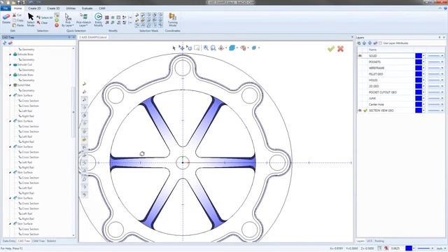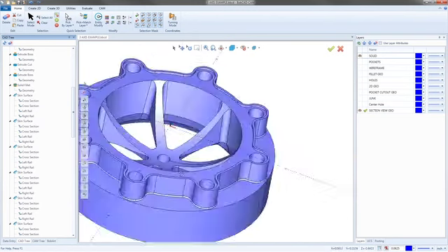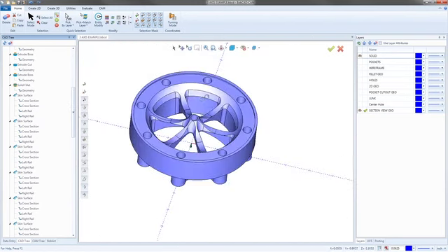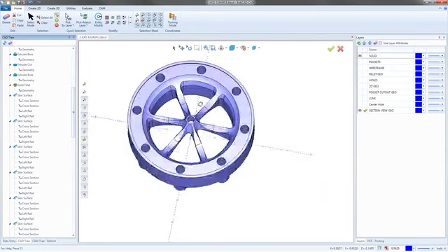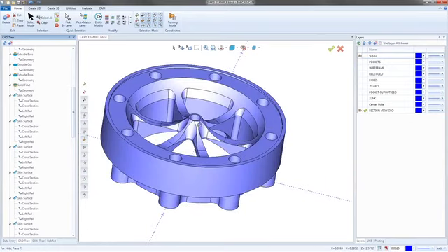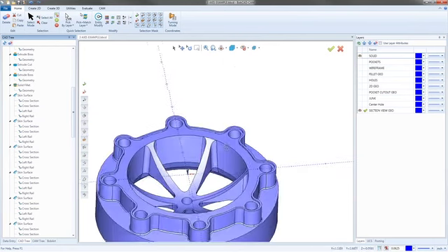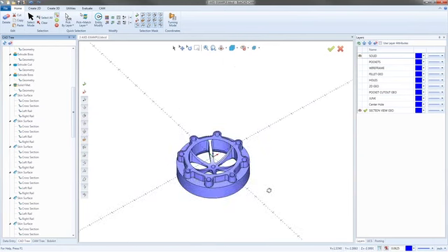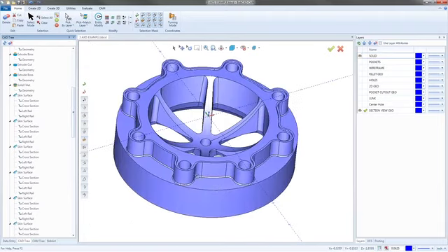In this top side, it's flaring out to the top. So you got an opening wider on the top than the bottom. But then when you flip it over, it's the same kind of thing. The flare goes to the top. So we should be able to machine everything from two different origins, one from the top, one from the bottom, and that should do the whole part. I don't suspect any other setups that we'll have, but I've been wrong before. So we'll find out when we get into it.